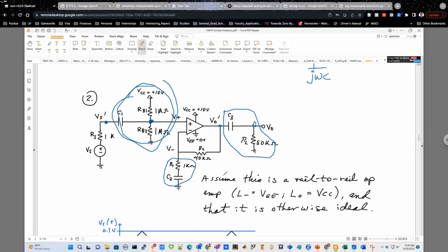The other thing that is important is that you have this RC circuit at the input side. What is the RC circuit doing? It's doing some kind of filtering as well, because any RC network will do filtering. And we learned in class that if you have a resistance in series and then a capacitance in parallel to ground, this forms a low-pass filter. Here it's the opposite. You have a capacitance in series and a resistance to ground. So it forms a high-pass filter. I'll not go through the equations because there's not much time, and I just want to talk about the important things. You can do the calculations and figure out why it is a high-pass filter and not a low-pass filter.